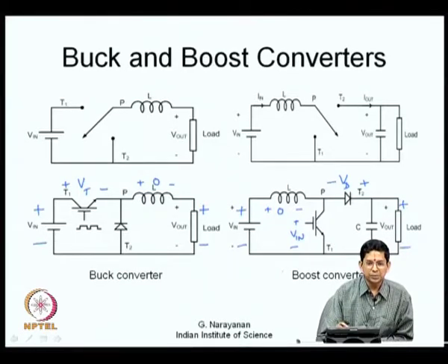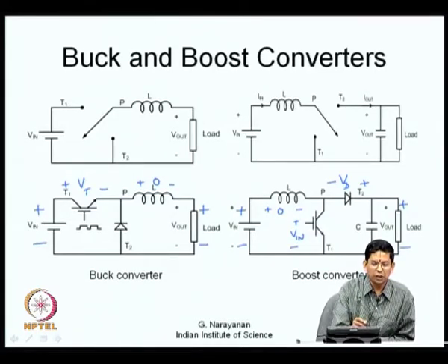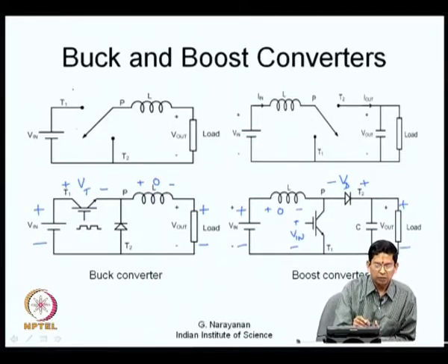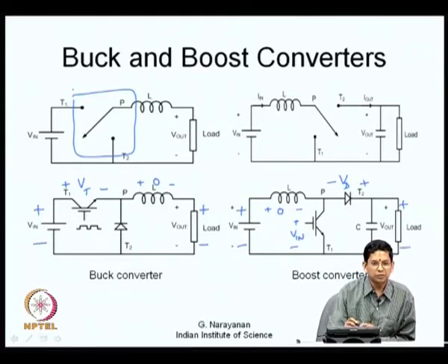What we are interested in subsequently is DC to AC conversion. So, what we want to see is to understand the basic rules by which we have come here. Let us take a look at how we came up with this DC to DC converter. We first asked what kind of switch is necessary. We understood that we need a particular kind of single pole double throw switch, and the next part is to understand how a single pole double throw switch can be realized.